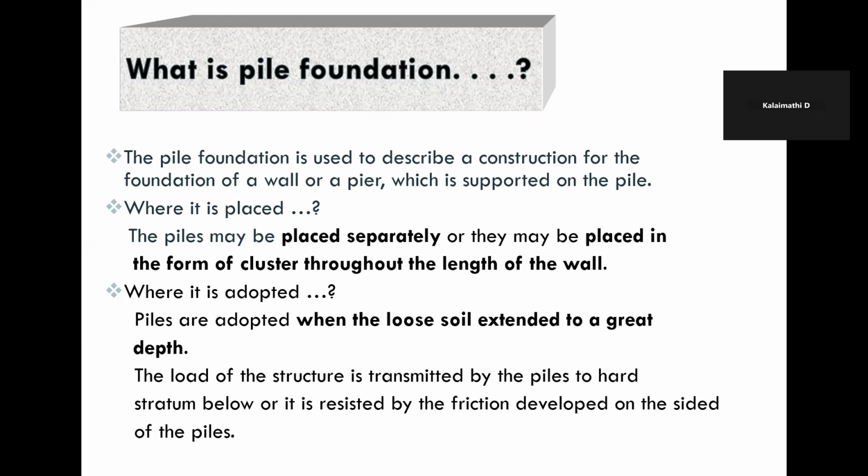A pile foundation is a type of foundation which is constructed deep into the ground and mostly will be available in circular sections. Shallow foundations rest on the ground and transfer the vertical loads directly to the soil. On such conditions, we can't use a shallow foundation, which would cause over tilting. So we opt for a deep foundation. One such foundation is called pile foundation.